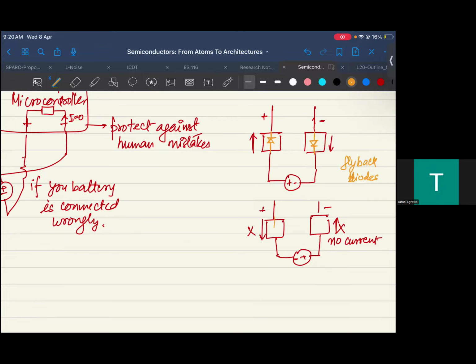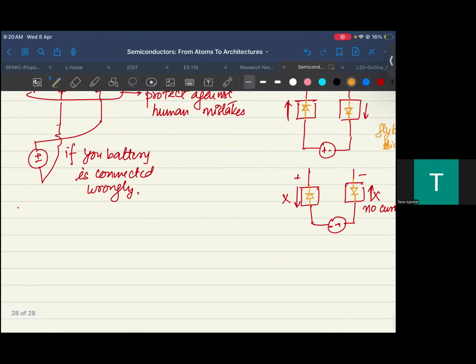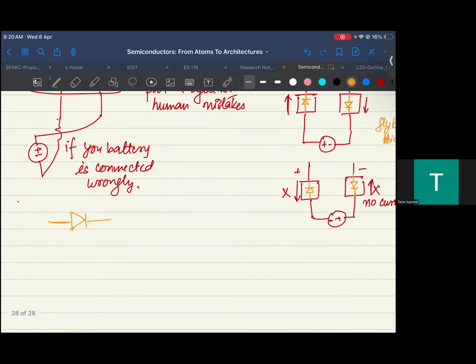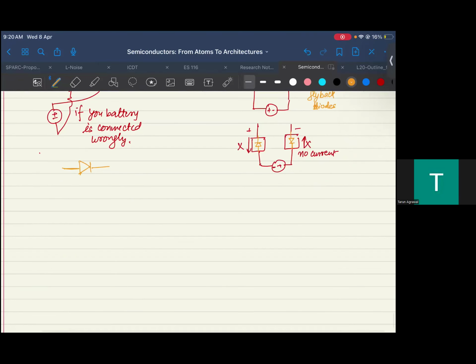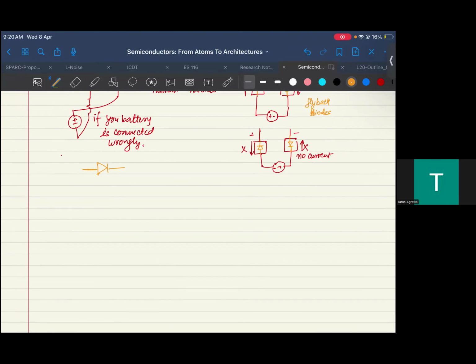So in the end, you would see how one designs these diodes. We have studied one way to design a diode, and this is what we were talking about in one of the junctions last time. We looked at how this could be physically designed, where we have an N-type silicon and we put a P-type silicon pocket inside it, and we put two contacts to this. This becomes my diode, right? So this is, let's say, the positive terminal.